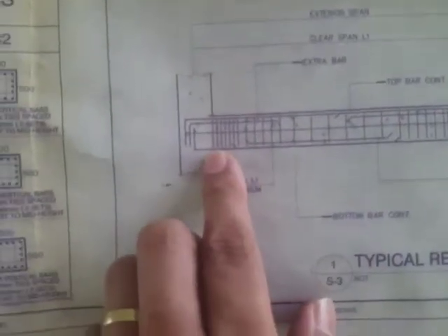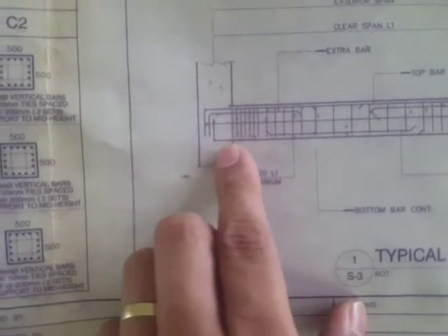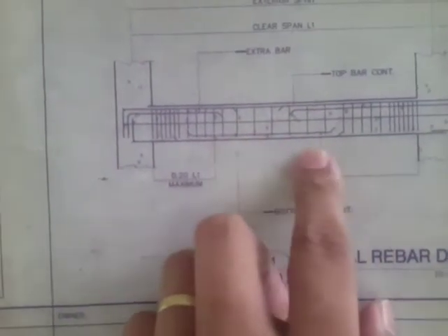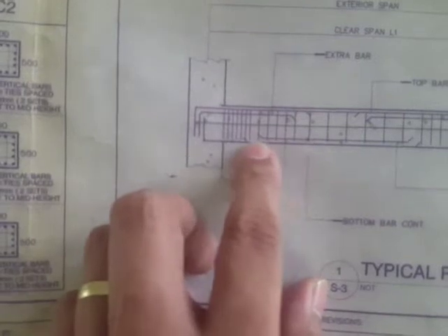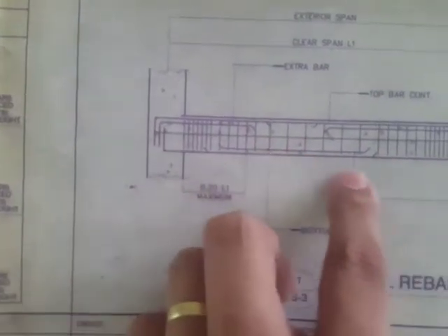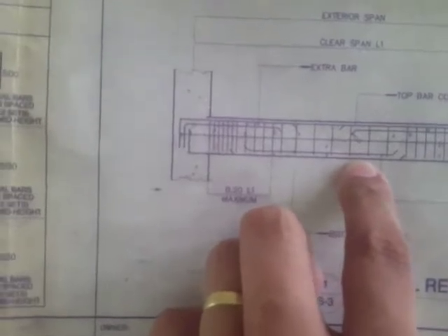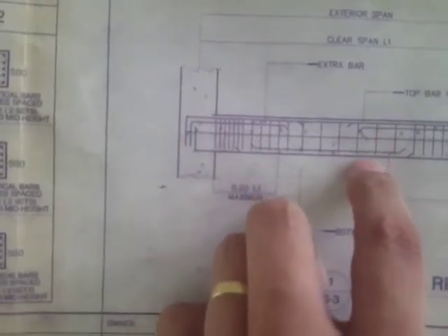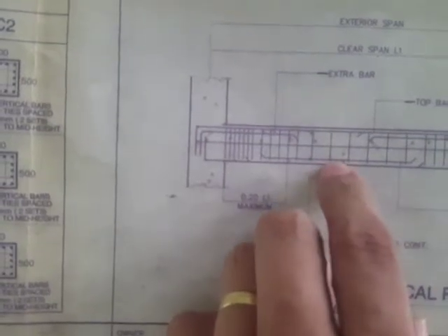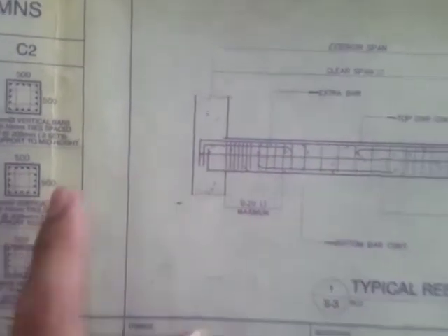So 5 at 50 mm, so meaning that the spacing is narrower as compared to the spacing at the mid span. Okay, so it says 5 at 50 and then 5 at 100. So this is it. Let's say 100, and then the rest is 250 spacing. So that's the spacing from this stirrup, this vertical line, to the adjacent vertical line. Okay, so that's it.